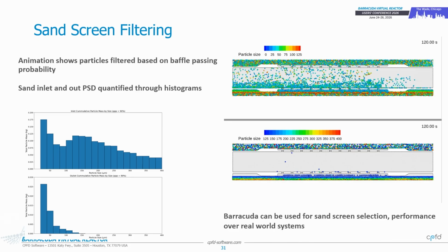You want to know what the outlet PSD is. As long as you're producing a lot of fines, that's okay. They will get suspended with the fluid because this is not gas, right? This is fluid. They get dragged down to the top, but you have heavier particles. You can start eroding away some pretty expensive equipment here.